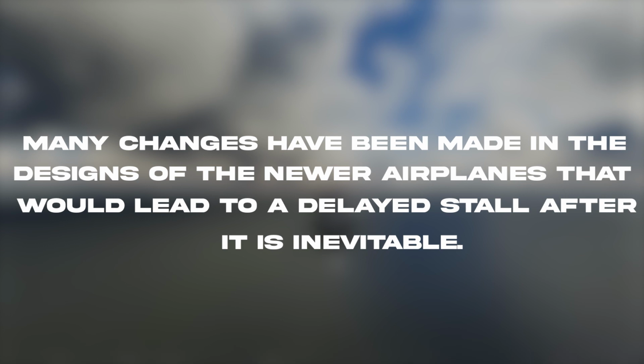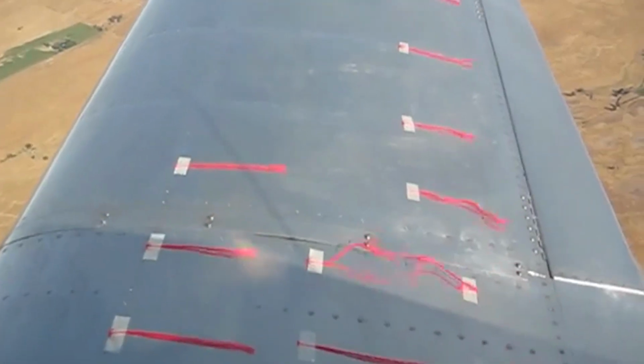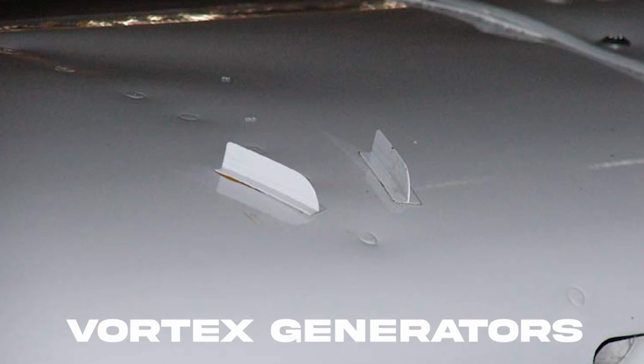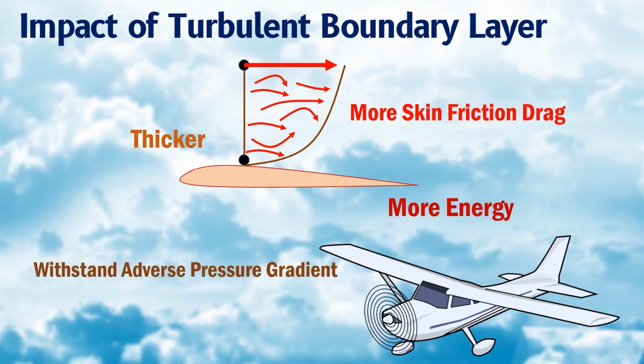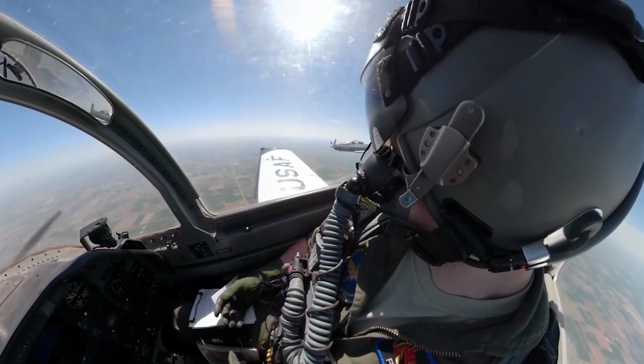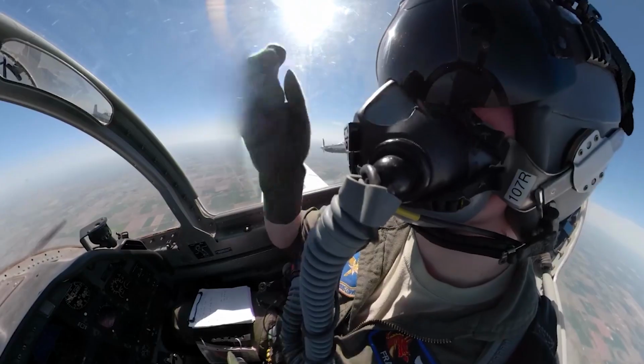These include things like adjusting the attachment of wings to the airframe such that it reduces a chance of tip stalls, using stall strips to cause the roots to stall faster than the tips, vortex generators that make it easier to fight the adverse pressure gradient. Using engine strakes also delays stalls. Pilots are also trained to recognize conditions signaling that a stall is approaching and control it.